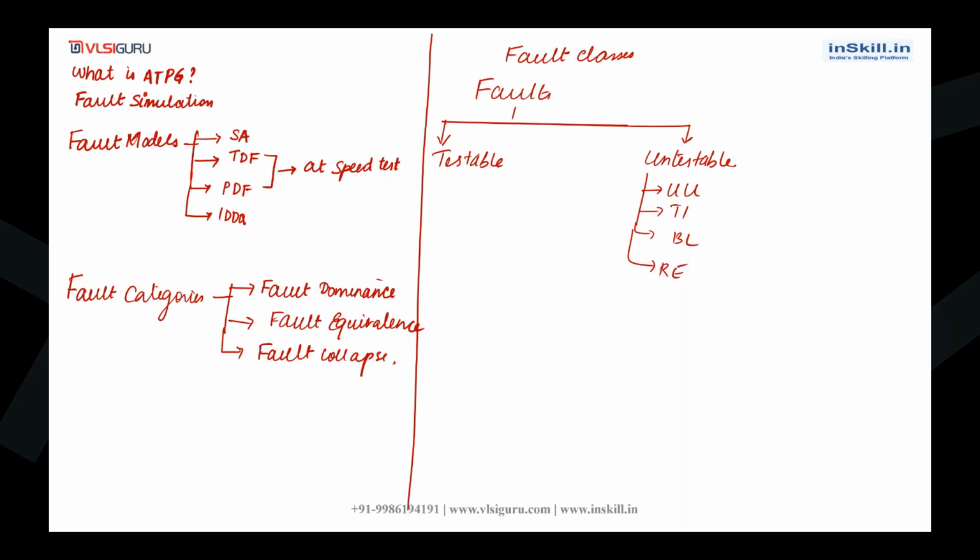Inside testable, you have subclasses like detected, which means detected by simulation, detected by implication, and the same way possibly detected, ATPG untestable, and then undetected.